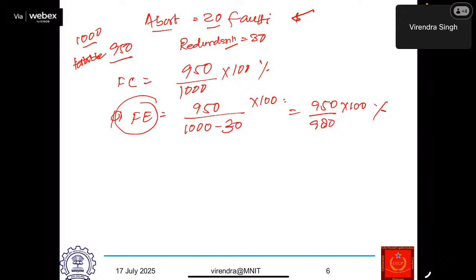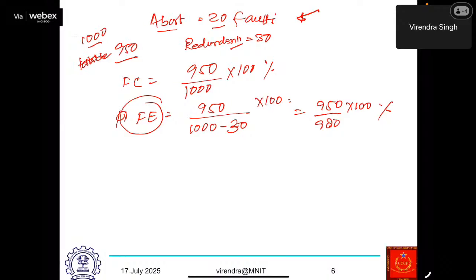So now in combinational logic we have some faults which are testable, some faults which are redundant, and some faults which we abort. We are aborting because I'm not putting enough effort to generate the test or declare that fault as redundant.